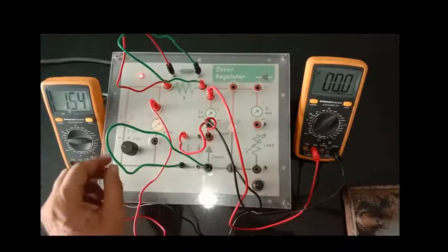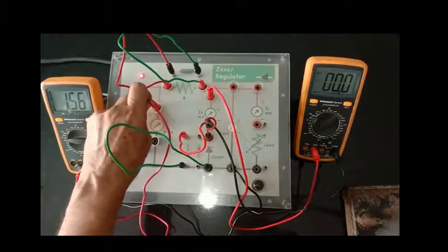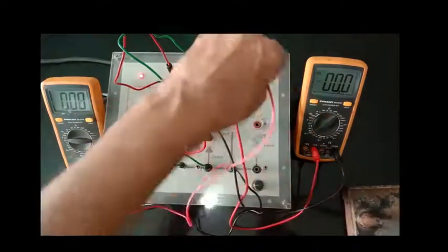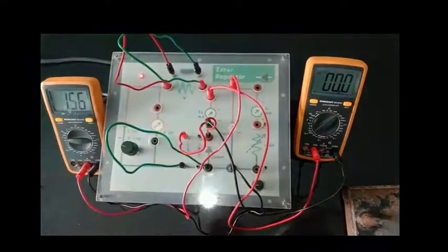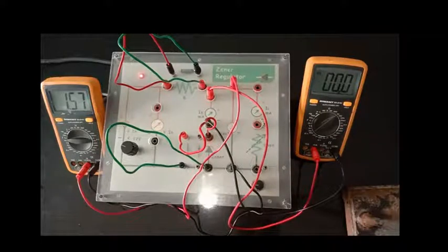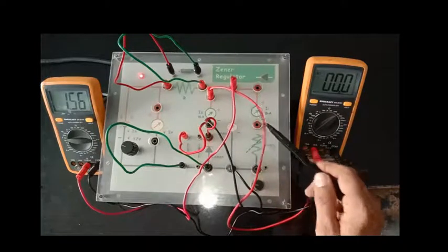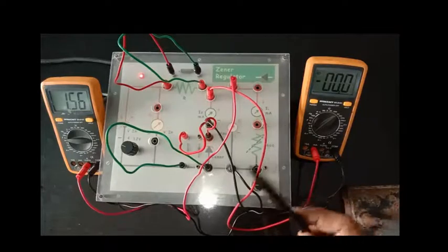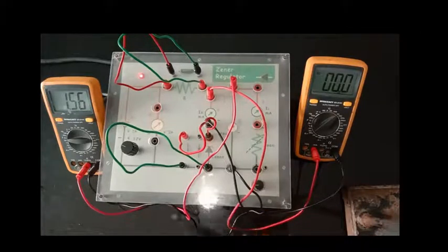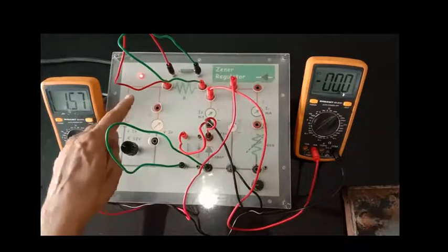The characteristic of a Zener diode, as you have seen in your PowerPoint presentation, has the I you are taking on the y-axis and the V you are taking on the x-axis. Zener is always connected in reverse bias mode, and therefore your current is negative, your voltage is also negative, and therefore your graph will fall into the third quadrant. Am I correct?